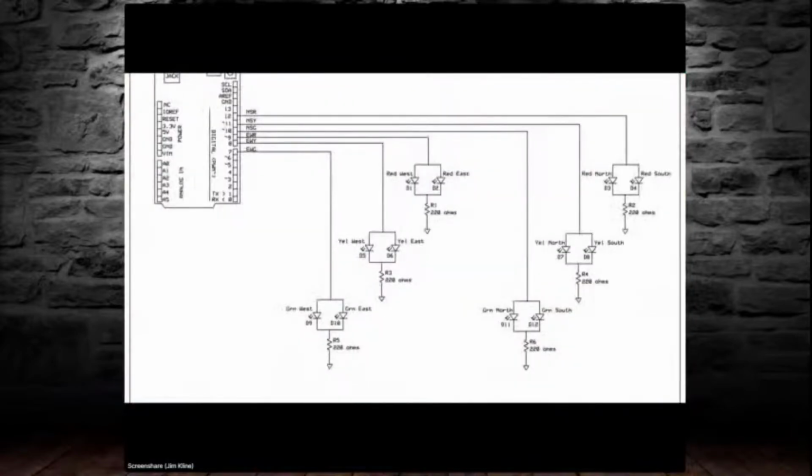This is an important step for a number of reasons, but when making a schematic, it is helpful to follow a recognizable format. The top-down order of the red, yellow, and green LEDs are in the same order as seen on an actual traffic light. It makes it easier to read the schematic. The Arduino will be supplying power to the LED pairs, and the drawing remains uncluttered by wiring the pins one after the other and not crossing any lines.